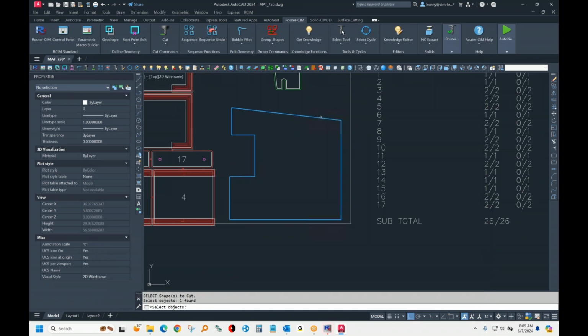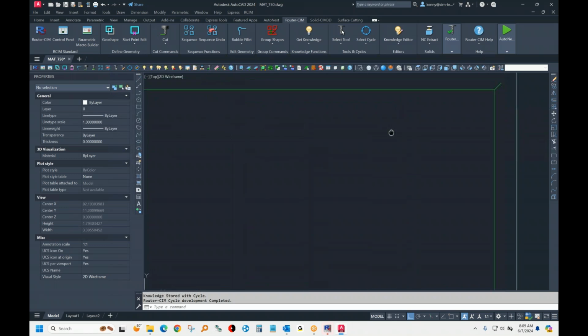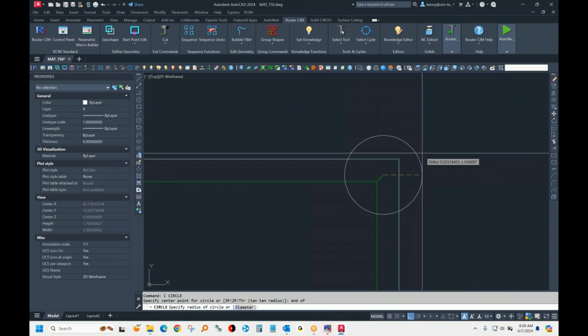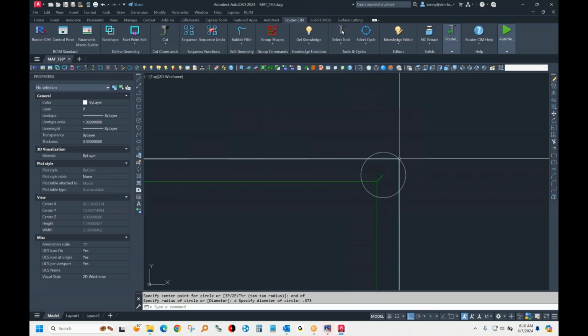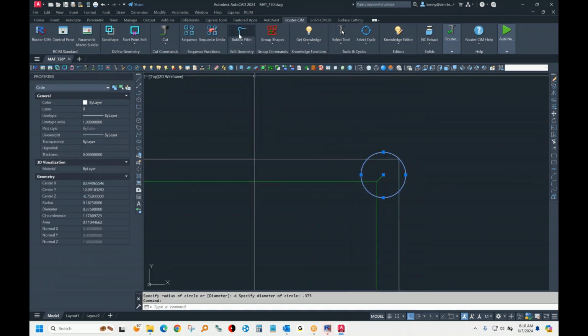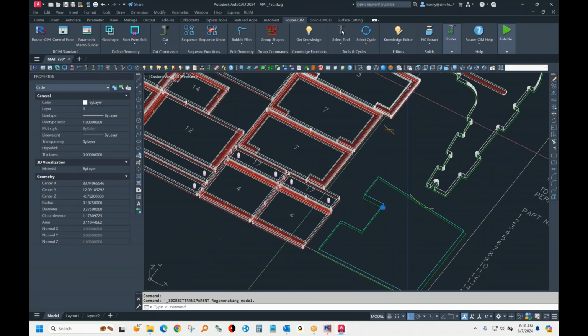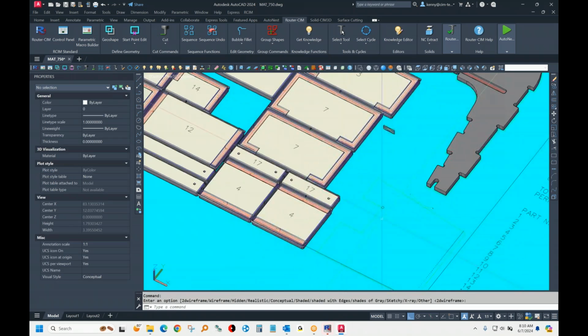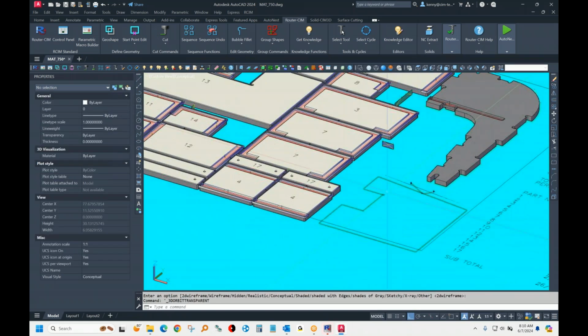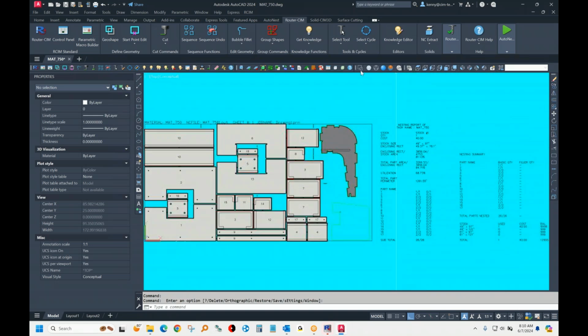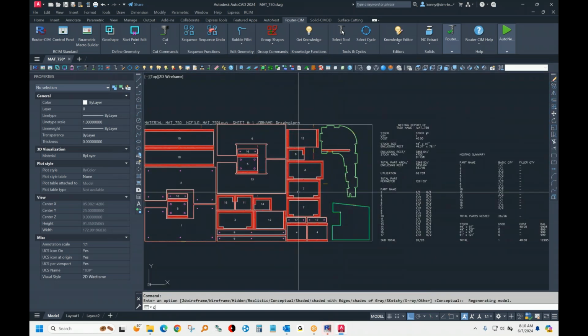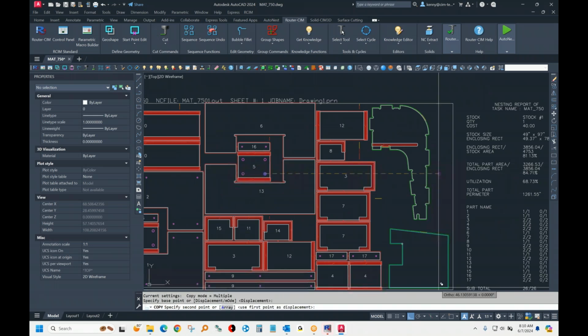And you make a cut, touch the part, and that did have that little corner punch thing turned on. So the tool's going to go into the corner here. There's a tool, 3/8 tool is going to come out to here so that you can, instead of drawing the bubble fillet, it's going to send the tool into the corner so you can put a square part in that corner there. Even though I drew that in 2D, the tool paths show up in 3D. So I got 3D solids and my 2D drawing in the same file. You can mix and match stuff like that. In fact, you can even just take, let me copy this drill hole and put it on my part here and here and here. So you can copy tool paths as well.